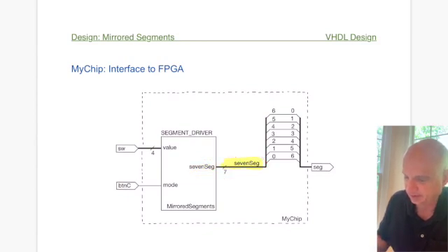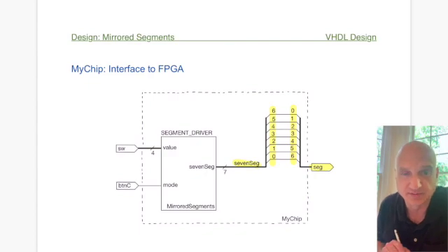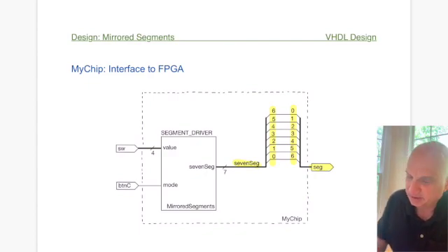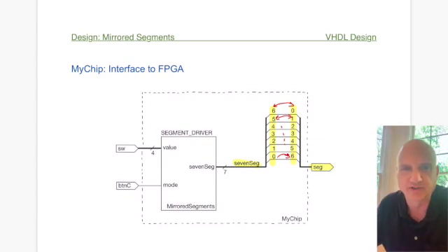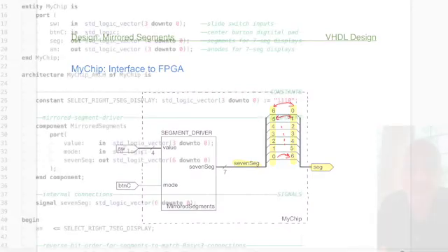So basically, we have these bits from our 7-segment signal being attached to these bits of our segment signal that goes to the Basys board. And you'll notice that bit 6 of the internal design connects to the Basys board's bit 0 for their segments. Bit 5 connects to 1, and all the way down until bit 0 connects to bit 6 on the segment component. So we basically inverted or swapped the bits around, and we can easily do that in VHDL using our concatenation operation. So let's look at what this would look like in code.